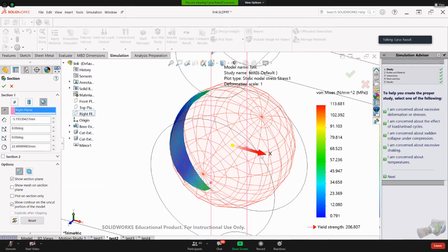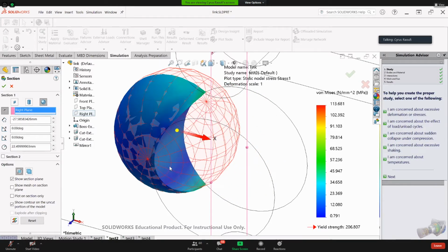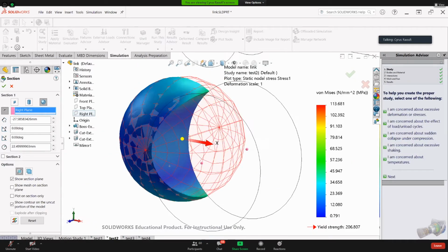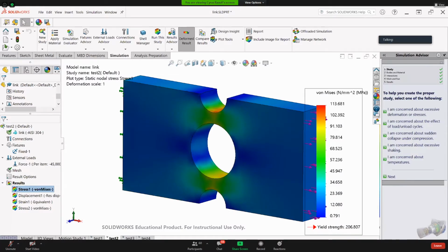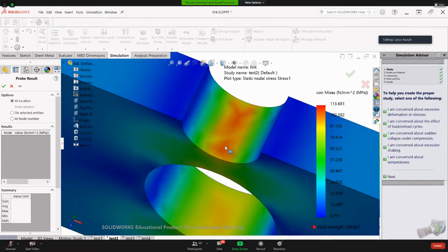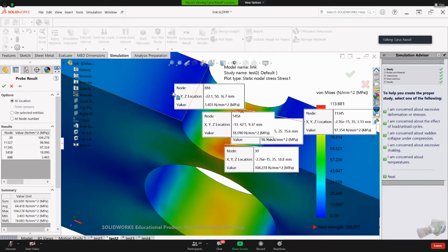See, you can see this out. I can move this cylindrical shape and can see that cross section here. See? Those are things that we have in section clipping. Probing is another tool that we have. We can go here and probe the result, can move on, and you can probe wherever you want. That is like a sensor, measuring the value at a selected point.